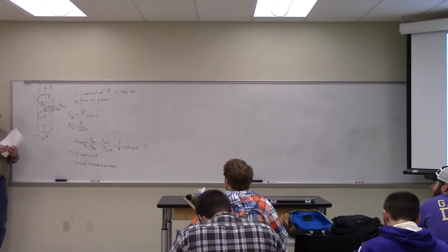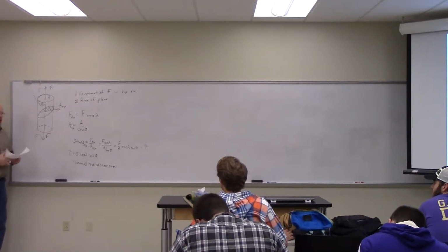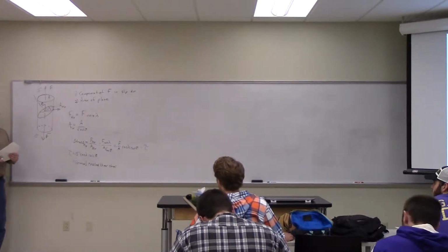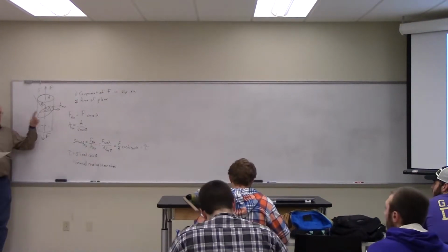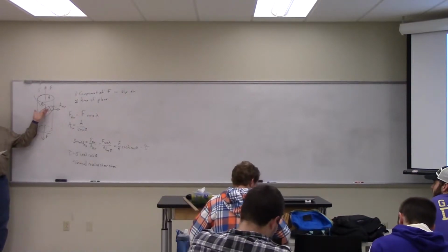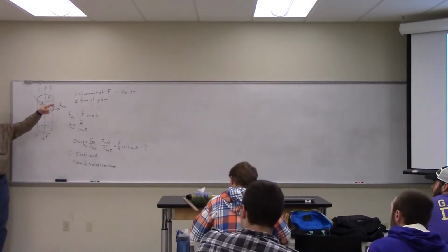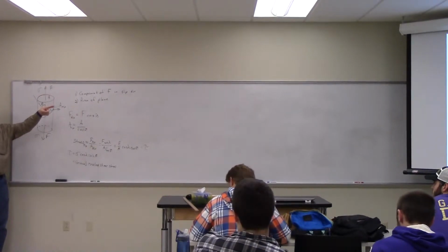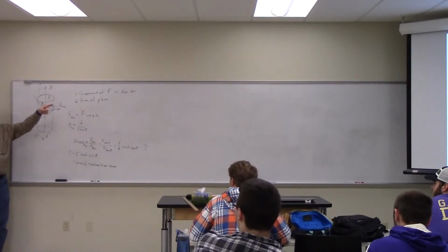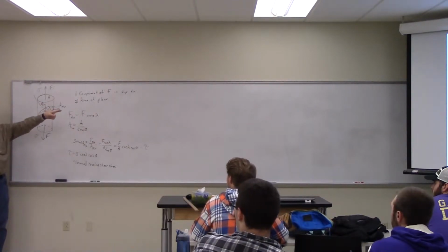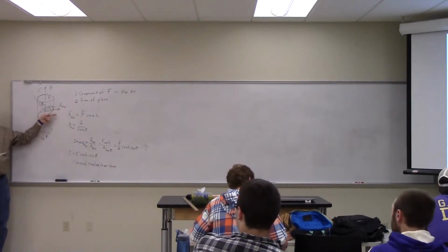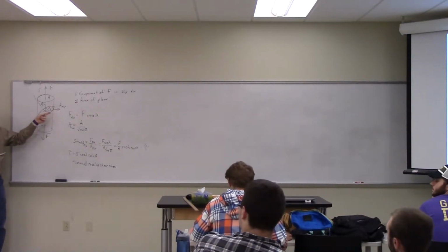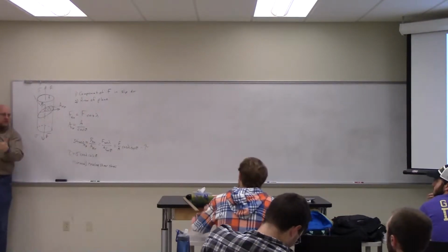So the resolved shear stress is the component of stress resolved to cause shear in the plane that we're interested in. The critical resolved shear stress is the one of those that gives me, because there's multiple slip systems, right? How many FCC slip systems are there? 12. There are 12 slip systems in the FCC. Not all of them are going to have the same lambda and phi, or empty set, right? They're all going to be different orientation.